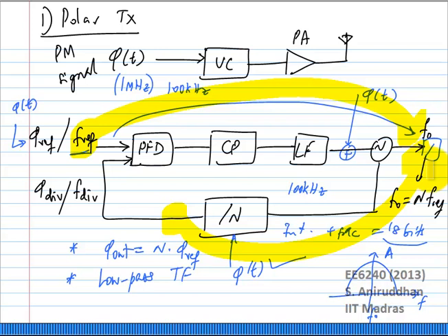Nowadays we know that most PLLs have fractional dividers which have sigma deltas inside them, and this sigma delta normally has the fractional number that actually goes into it. So depending on what exact frequency you want to achieve, you have a certain integer number and a fractional number, the division number, that goes into this divider, and along with this static number you can also give it a dynamic number which will decide how the division ratio varies, and therefore how the output phase and frequency vary. Is that clear?